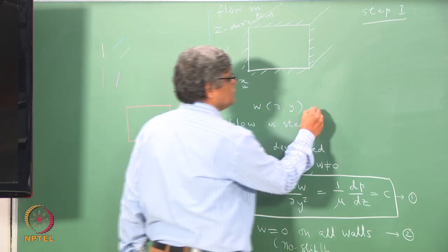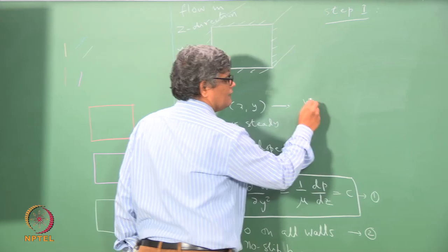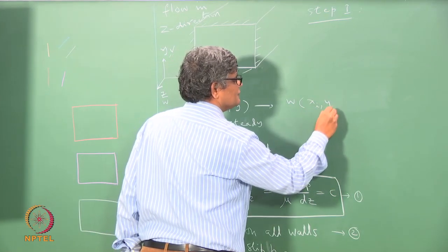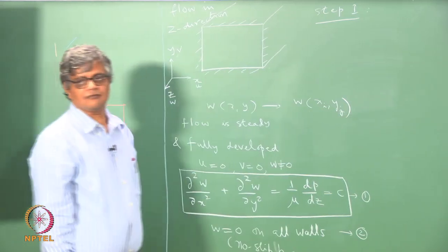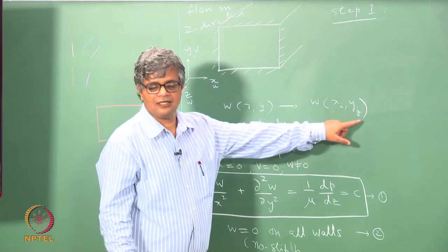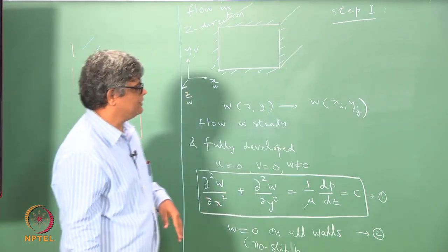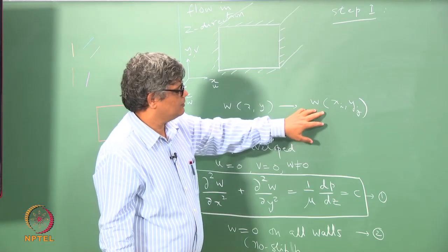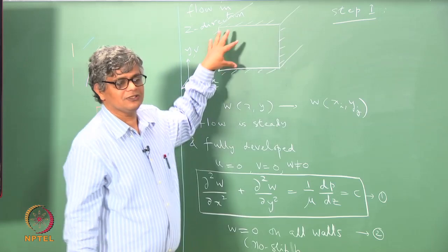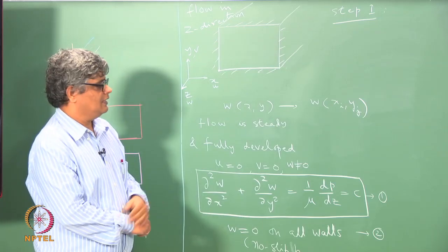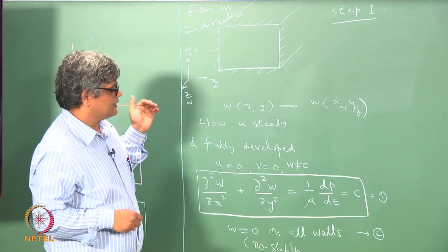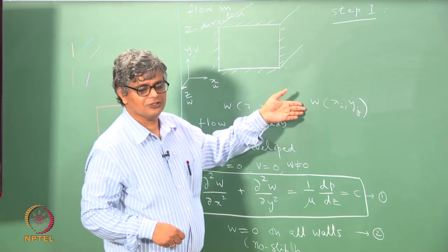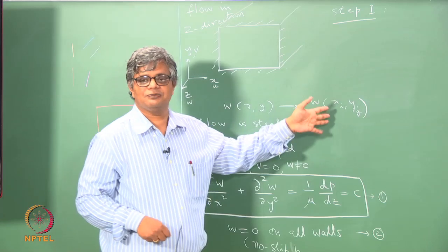We are only going to give a value of W at certain specific locations. Okay. These locations are essentially what we call grid points. So, within this domain we give the value of W at many points which are spread around this. Instead of getting a continuous solution of W, we get a discrete solution of W at pre-specified grid points